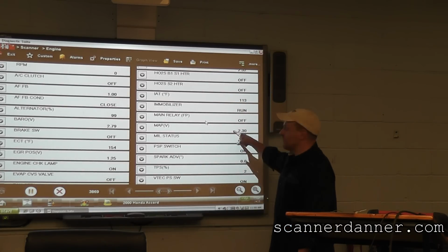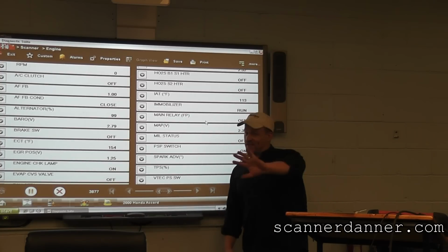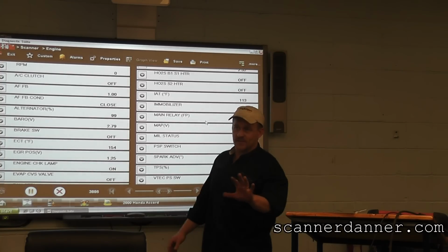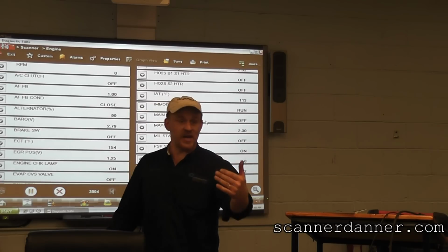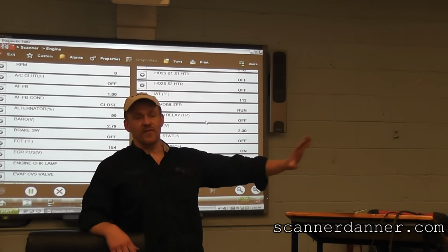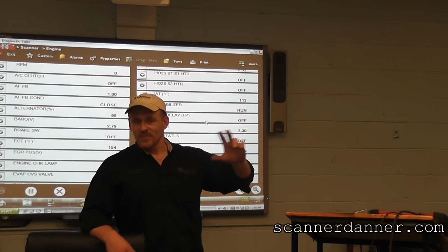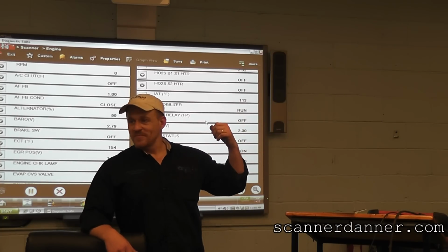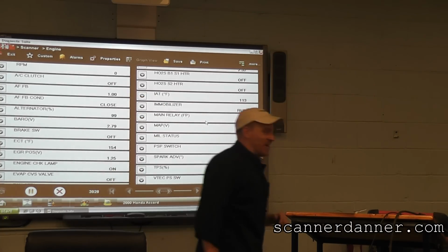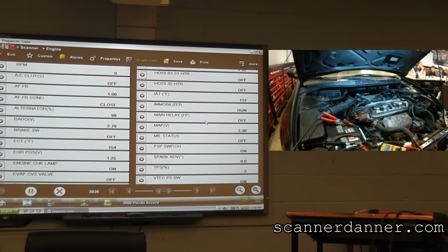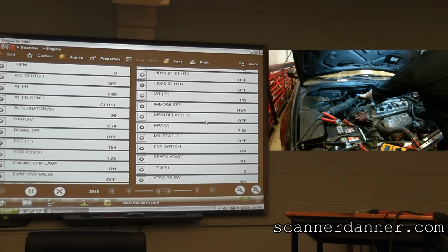Watch the MAP. I've watched for that. Okay, a MAP sensor, guys, listen, if that's the case, a MAP sensor is a pressure sensor, right? Measures pressure changes. If I would go over here with the engine off and open and close the throttle, should my MAP voltage change? No. I'm going to do that. Well, we might need an RPM signal, but watch the throttle.